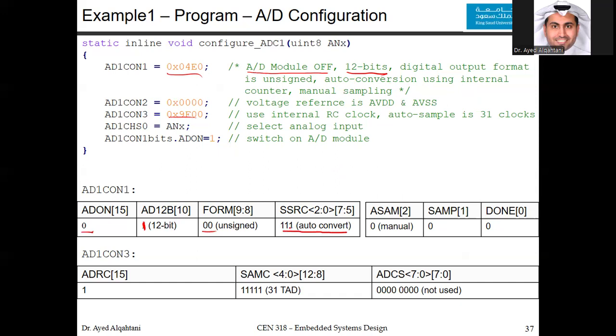And the obvious choice for the sampling, remember, this is an analog signal, and the potentiometer you move mechanically using your hand. So there is no point in sampling automatically, like hundreds, maybe thousands of samples per millisecond. There won't be somebody who's that fast changing the potentiometer mechanically.